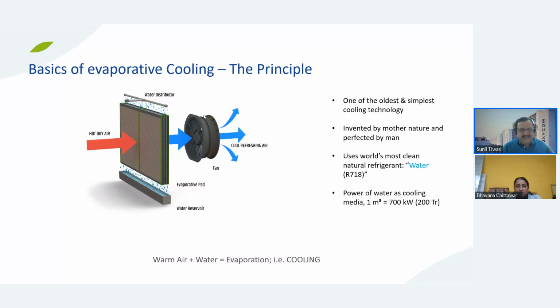And the principle is very clean. You have hot and dry air passing through a wet surface where the water is retained. In the process, the air picks up some moisture and its temperature drops. So that's an adiabatic process.